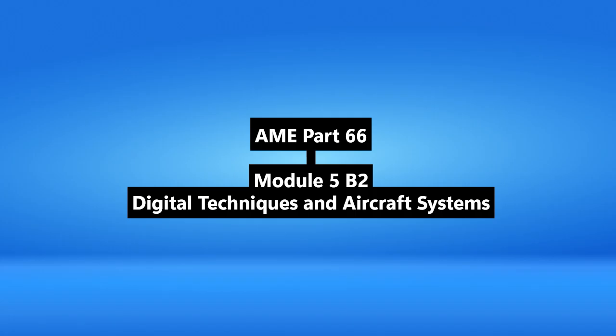ACARS. Aircraft Communication Addressing and Reporting System. It's a digital datalink system for sending short messages between the aircraft and ground airline operations, maintenance data, automatic reporting of flight phases like out, off, on, in times, OOOI. IRS. Inertial Reference System. Uses gyros and accelerometers to sense motion, rotation, and acceleration. From that, it calculates the aircraft's attitude, heading, velocity, and position. Modern ones are strap-down systems using laser gyros or other solid-state sensors feeding data to computers rather than complex mechanical gimbaled platforms. But they drift, right?